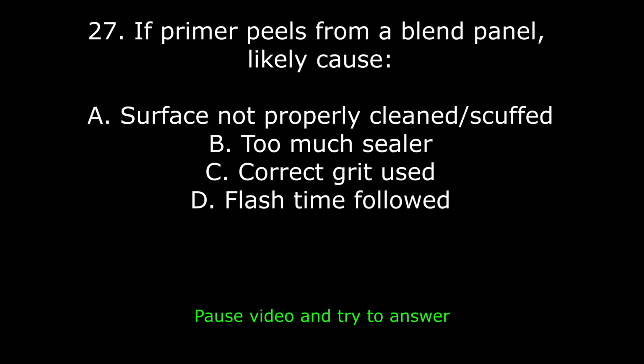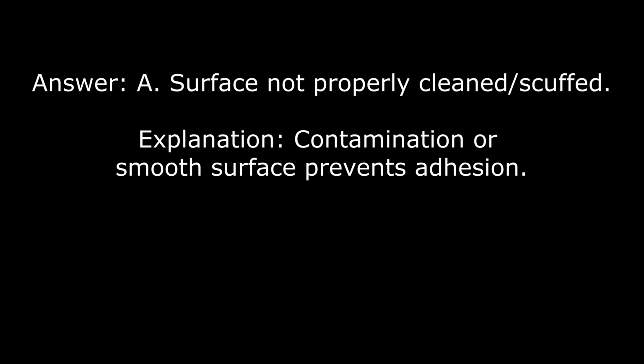27. If primer peels from a blend panel, likely cause: A. Surface not properly cleaned or scuffed. B. Too much sealer. C. Correct grit used. D. Flash time followed. Answer: A. Surface not properly cleaned or scuffed. Explanation: contamination or smooth surface prevents adhesion.